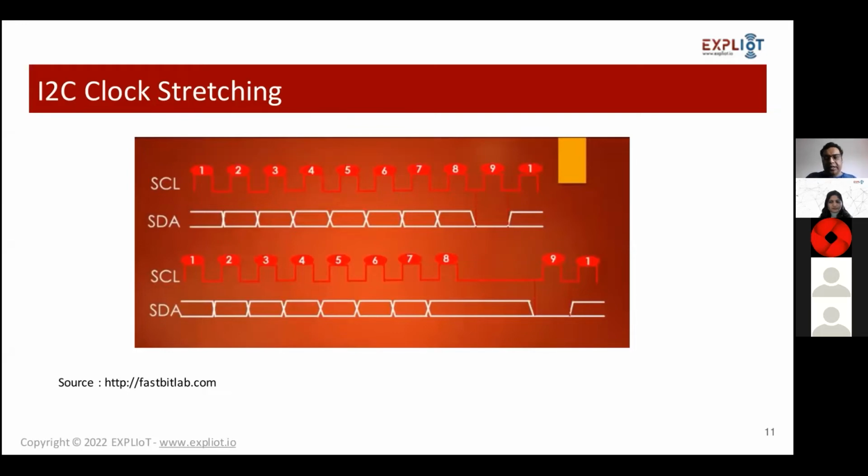So one feature that the I2C specification provides is called clock stretching, where either a master or slave can pause the I2C communication by pulling the clock line low for some amount of time. This way, you have sufficient time to handle that particular 8 bits of data and prepare for the next byte of communication, where you are again getting data from the transmitter.